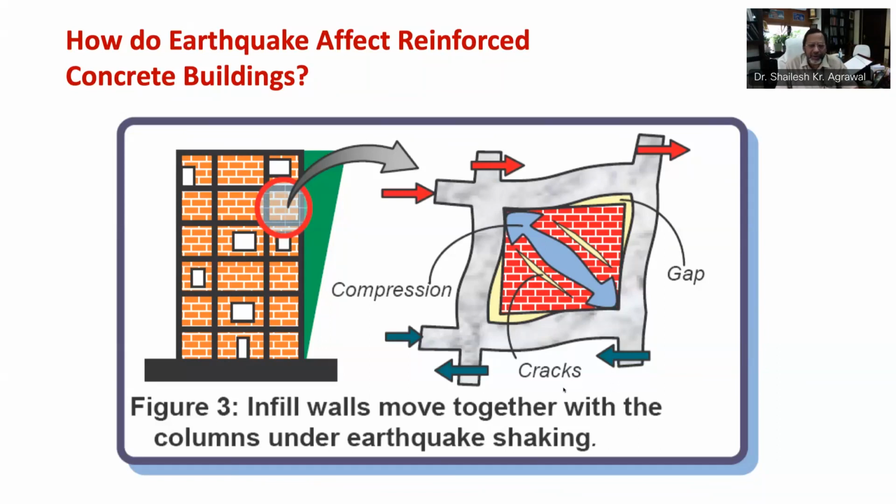The earthquake performance of infill walls is enhanced by mortars of good strength, making proper masonry courses and proper packing of gaps between RCC frames and masonry infill walls. However, remember, an infill wall unduly tall or long in comparison to its thickness may fall out of plane, which means in its thin direction. This out-of-plane failure can sometimes be life-threatening and should always be avoided. Also, infill irregularity in the building causes other ill effects such as torsion, stiffness irregularity, short column effects, etc.